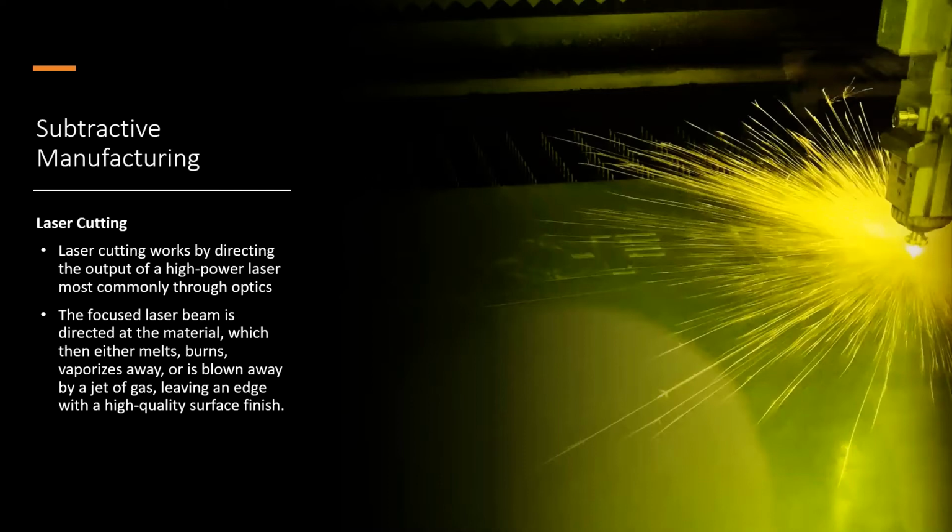The other one that you hear frequently is the idea of a laser cutter. A laser cutter is really a more advanced and faster version of a CNC. Instead of using a mechanical tool as its cutting method, it's using a laser. The laser works to melt the material in a very, very fine way to create the shape that you're trying to create. Often in the picture here, they're cutting some words out of a piece of sheet metal of some kind. So the laser will cut all this out.